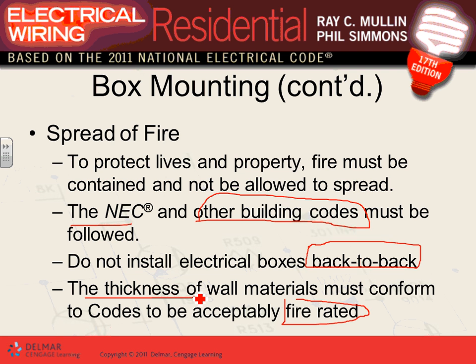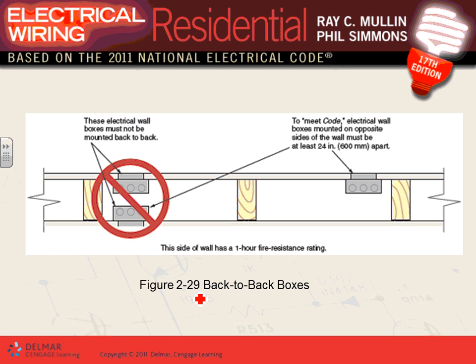If you get into 2 and 3, you're talking about block and concrete walls. So if you have a wall that's a 1 hour fire rated wall, double sheetrock typically, then in a situation when you penetrate, when you make a hole in it, you're supposed to maintain the integrity of this wall. For example, this side of the wall is a 1 hour fire rated wall. Can you guys see that? You're going to a none, and this one is not.